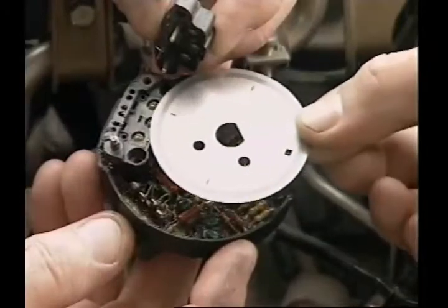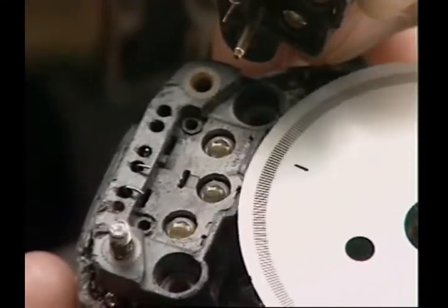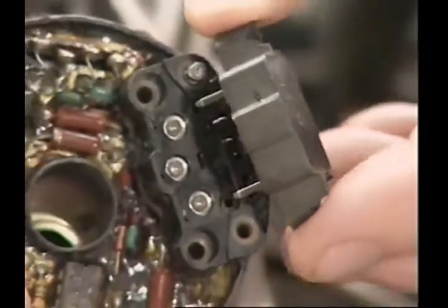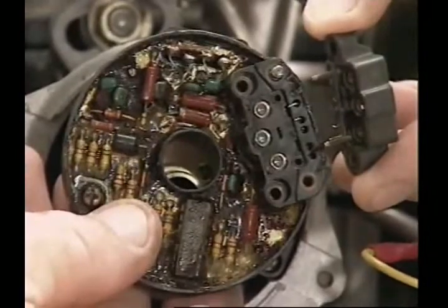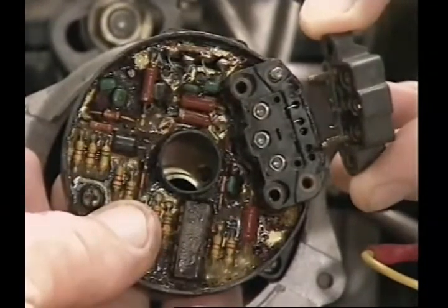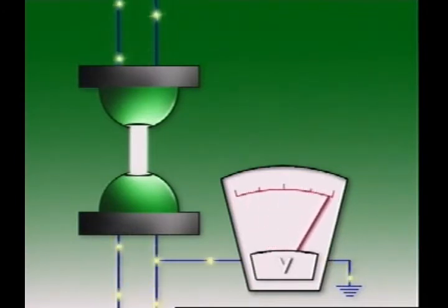As the rotor plate turns, it passes between 2 sets of diodes, positioned in line with the slits. The diodes above the rotor plate are light-emitting diodes, while the ones below are photodiodes. When provided with a suitable voltage, light-emitting diodes transmit a fine beam of light. Photodiodes receive this light and use it to make a voltage output signal.